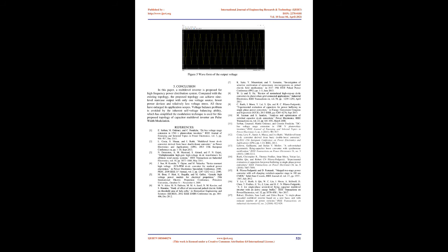The functioning model of the proposed system is shown in Figure 2. This figure shows the proposed 9-level inverter, which consists of 2 stages. The circuit in the front end is a developed switched capacitor circuit, DSCC, which is different from the basic SC cells in that it can output more voltage levels with relatively fewer components. An H-bridge circuit, HBC, is used in the backend to change the polarity of the front-end output. In ideal circumstances, the proposed inverter has 9 output voltage levels and to achieve this goal, only 1 DC voltage source, 2 capacitors, 2 diodes, and 9 power switches are needed.